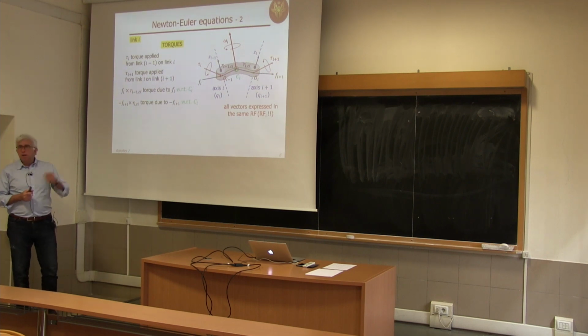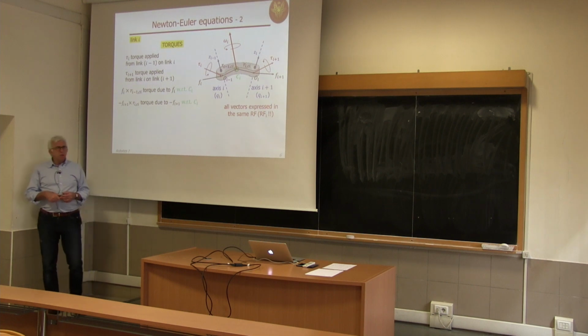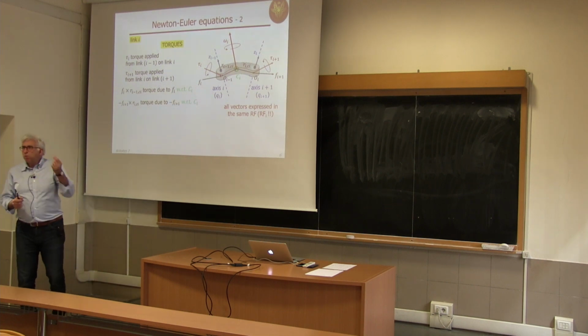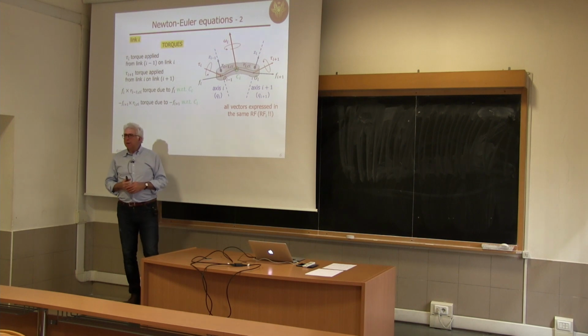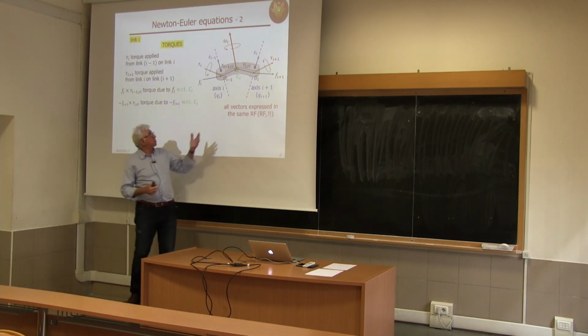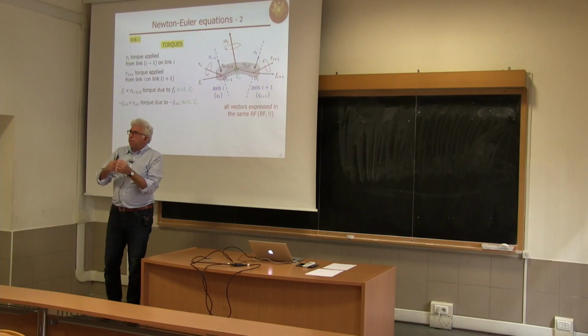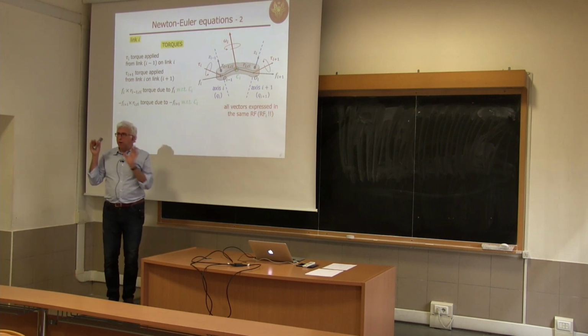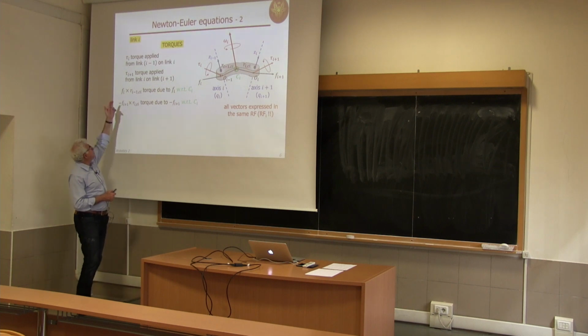And now we have to define some point with respect to which we express the resulting torques. We could use any point, but it is convenient to use at least one point where one of these forces vanishes, so the line of action of this force is passing through this point. And here we have three possible choices. The common one will be the choice of the center of mass. Because if we consider the center of mass as the point through which we compute the effect of torques of forces applied to the body, the gravity term will vanish because its line of action is passing exactly through the center of mass. Okay? So we have defined tau_{i+1}.